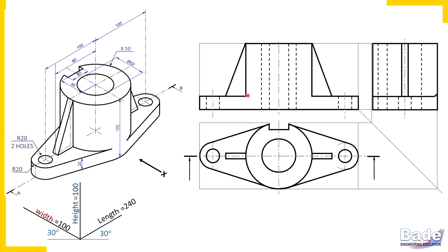So what you studied here up till now in sectional views, try to understand. In sectional views, for the portions of the object which get cut, the boundary between those portions we must erase. Such boundaries will not appear in sectional views, remember.